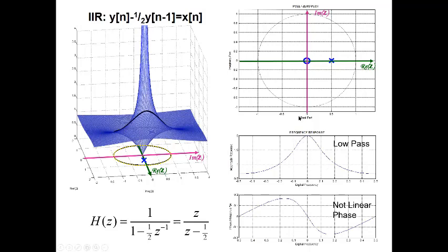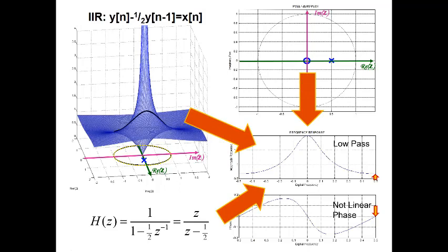And so what we see as we move around the unit circle and look up at DC is the highest peak in the magnitude response. As we move around behind here, we see the rubber sheet getting pulled down lower and lower. The point is that it's the pole and zero locations that are pulling and pushing on that rubber sheet, and what it's doing above the unit circle translates into the shape of the magnitude response of the system.